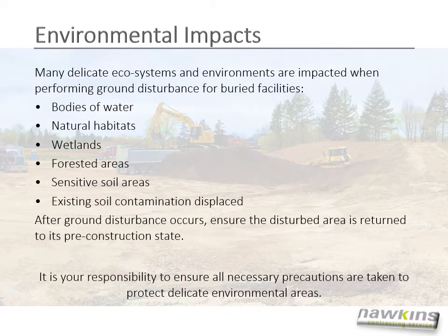When performing ground disturbance, we must also consider the environment. Many delicate ecosystems and environments are impacted when performing ground disturbance for buried facilities, such as bodies of water, natural habitats, wetlands, forested areas, sensitive soil areas, and existing soil contamination being displaced. After ground disturbance occurs, ensure the disturbed area is returned to its pre-construction state. It is your responsibility to ensure all necessary precautions are taken to protect delicate environmental areas.